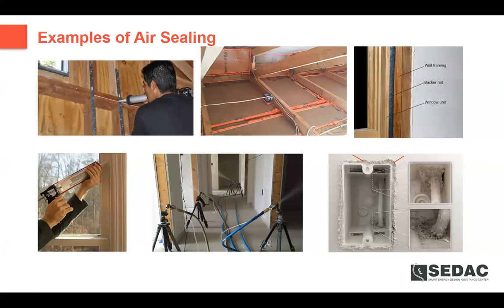And you can see on the bottom right side where these particles have collected around the perimeter of the box there, and inside the box where the wires penetrate to the outside of the box and into the cavity, where all these little particulates have collected and sealed the leaks. Thank you, Ryan. It's not that we're saying everybody should be doing this, but it's just something for your own knowledge, and it's called AeroBarrier.